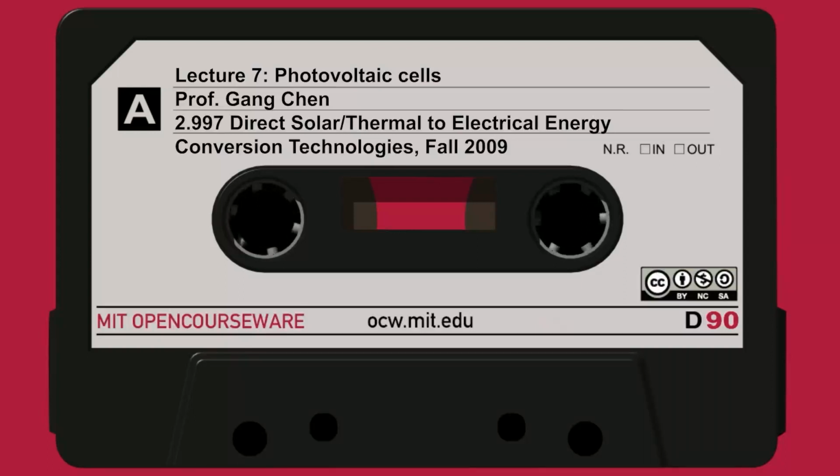So that's why we want it that way. You want to have a longer potential field, to use the field to drive the carriers. I'm talking about the picture right there, a thin and flat PN junction. With a really thin PN junction, of course, the good thing is your electrode is very close. You can get the charge to the two electrodes, but your photon may not get absorbed.